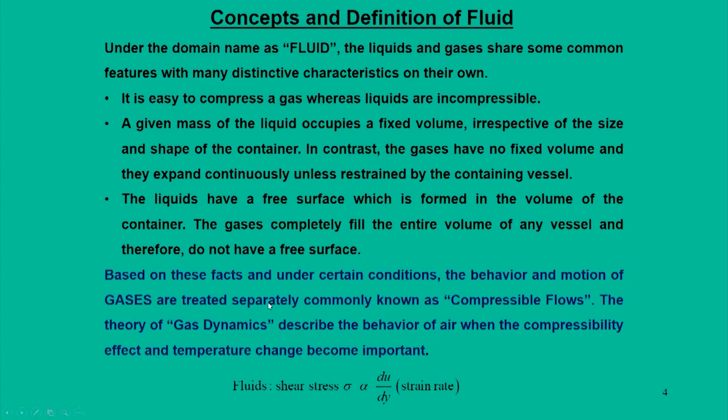So, based on these facts and certain conditions, one can say that the behavior and motion of gases are treated separately, and they come under the broad name of compressible flow. In fact, gas dynamics is another analogous term associated with compressible flows. The theory of gas dynamics describes the behavior of gas, and in our course we will talk about gas as air, when the compressibility effect and temperature change become important.